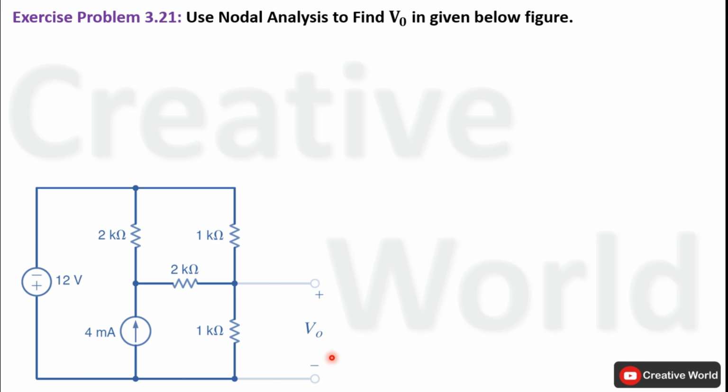We know that in order to apply nodal analysis on any network, we have to follow some steps. The first step includes finding out the maximum number of node voltage equations that can be retrieved from that network. Using this equation, we can find out that figure. In this equation, n represents the number of nodes in the network. In this network, there are 4 nodes, so 4 minus 1 will be equal to 3. A maximum of 3 node voltage equations can be retrieved from this network.